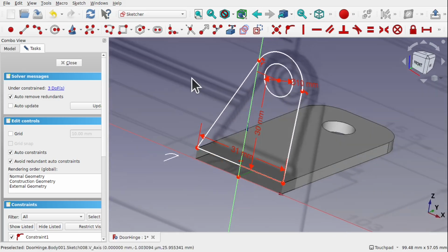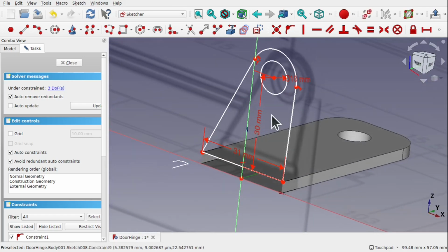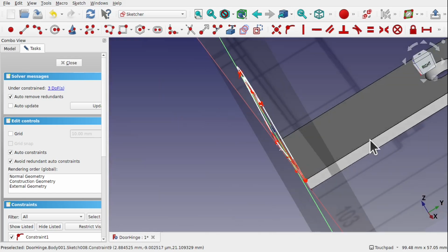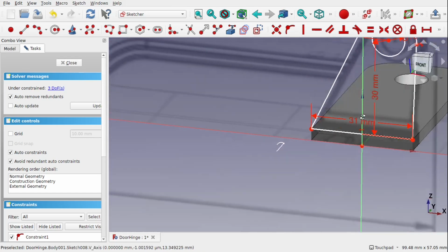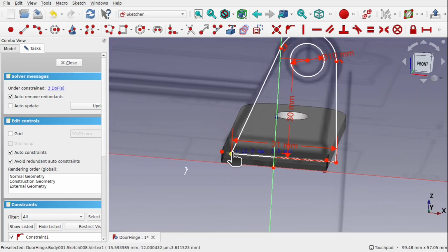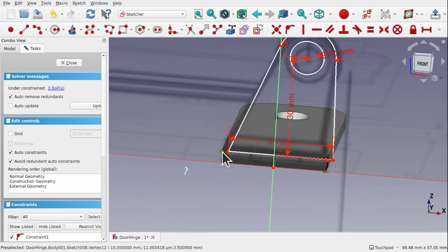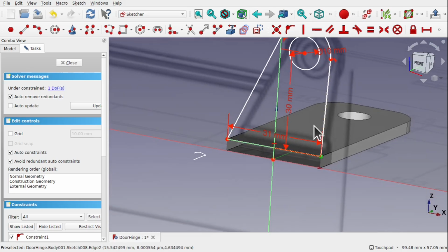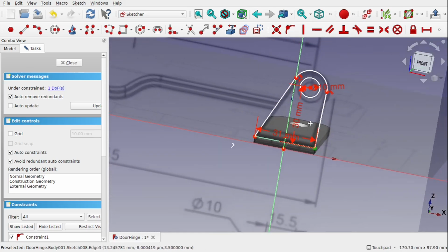Remember, we have got this image plane. So if you have problems trying to get to those points, then it might be worth coming in, hiding these image planes, or coming around to the other side and pulling in geometry from here. So now we've got those points in, we can take the points, make them coincident, and the same for this side. Well, we don't have to do it for this side, so that's fine because we've got a length in there.